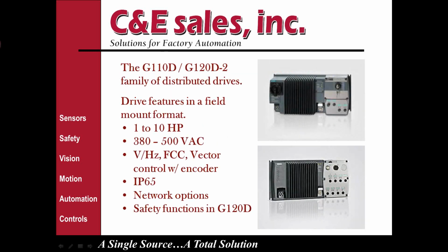The next family that we'll talk about is the G110 and G120D drives. These are enclosed, if you will, or distributed drive feature. It's intended to be mounted right out on the machine. They're used quite often for conveyor applications. Can also be used for pump applications.